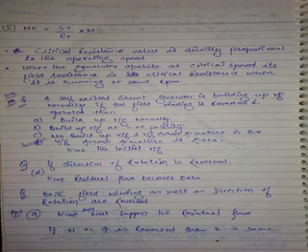Will the residual flux be assisted or not? Yes. There is no neutralization of residual flux in this case, so no problem with the build-up of voltage. But what has happened here? Flux is reversed automatically, speed is reversed. So minus, minus. What is the voltage? Positive. It builds up voltage normally.